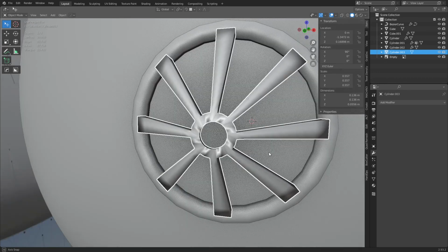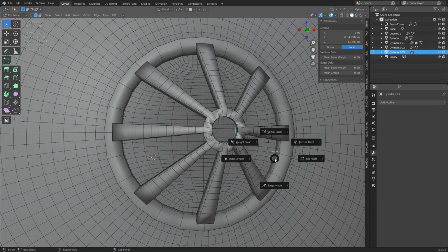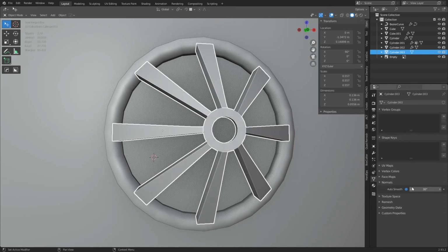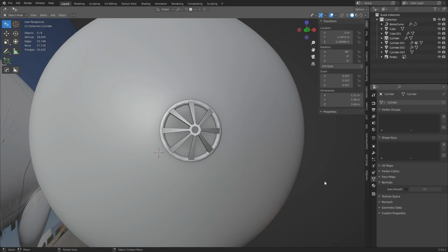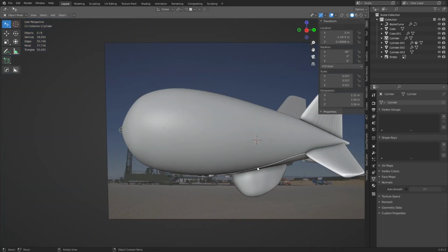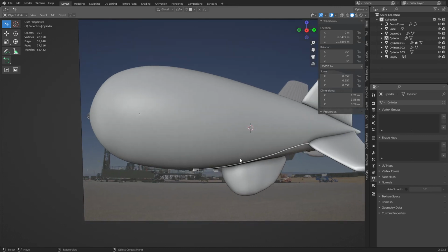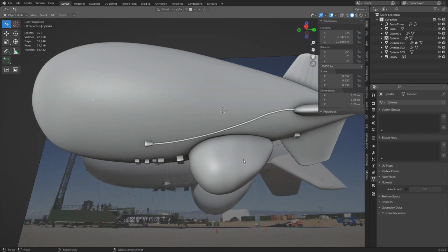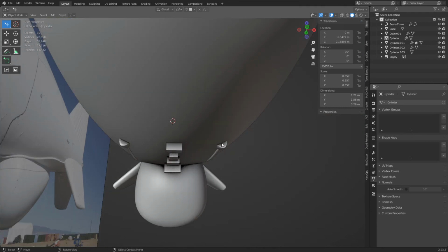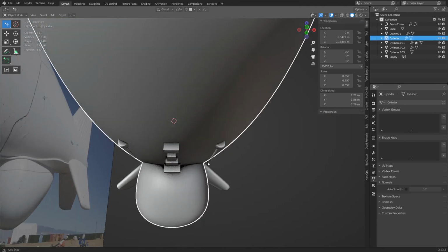And if you do smooth this, you'll notice that it's too low poly. Smooth is going to be kind of crappy, but go to normals, auto smooth if it's low poly. So like if you're doing this full size structure, you're adding all the little bars to it and all the other fun stuff, a lot of this being subdivided isn't needed.